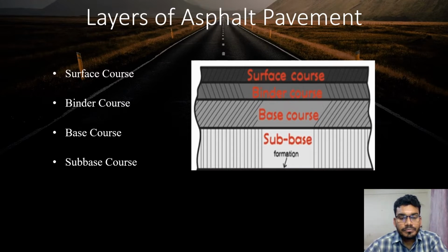For the binder course, the core function is to quickly and efficiently drive shear forces and vibrations from the road surface to the layers below. Thus, it protects the outer layer also. The base course is the layer immediately below the binder course. It provides additional load distribution and also contributes to drainage. Base courses are usually constructed out of coarse aggregate or hot mix asphalt.